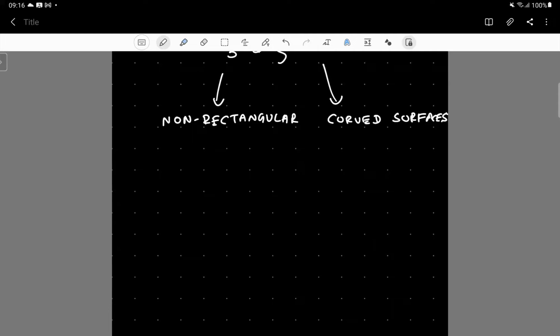simple beam elements, simple bar elements, linear constant strain triangular elements, or linear strain triangular elements. You might need to use more complex elements, or elements having a large number of nodes, higher order elements. You might need to use higher order elements to properly capture, if it is a stress distribution, of course, such elements might be required to capture stress distribution accurately.